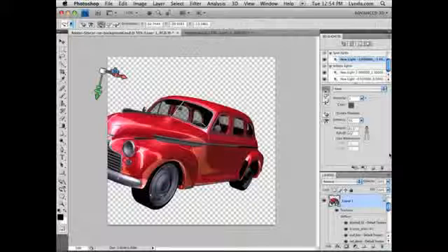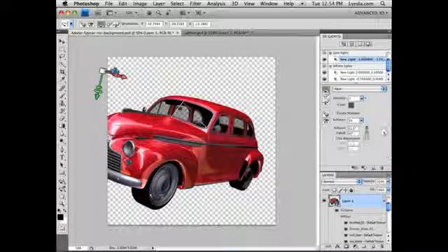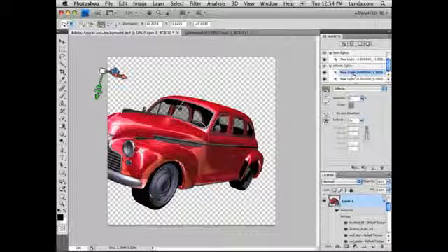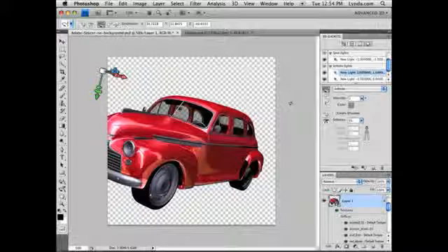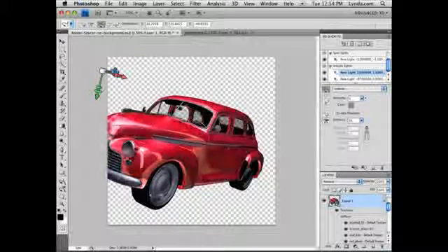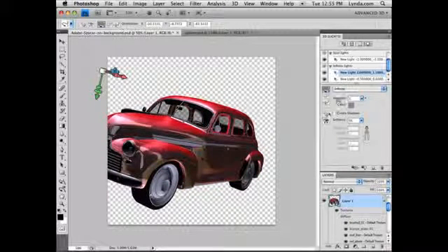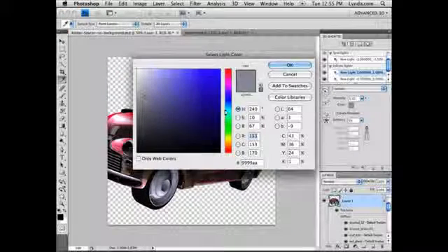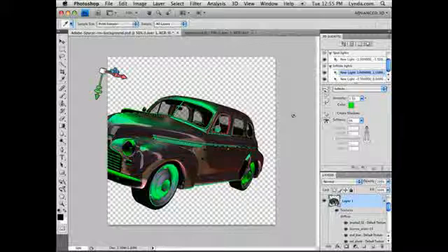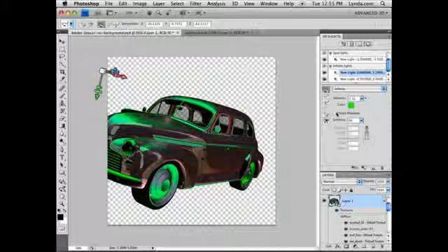Now we can also move and adjust the lights in our document. Let's say, for example, I select this infinite light. I can click on one of these navigational controls to adjust it. Let's say I click this top one to rotate the light. If I click and drag in my scene and rotate around, you can see that I'm actually changing how the light is hitting my 3D object. From the 3D panel, I could also click and drag to adjust the intensity of the light. I could also click in the color swatch to change the color of the light. And I could click Create Shadows to create shadows and adjust those shadows here as well.